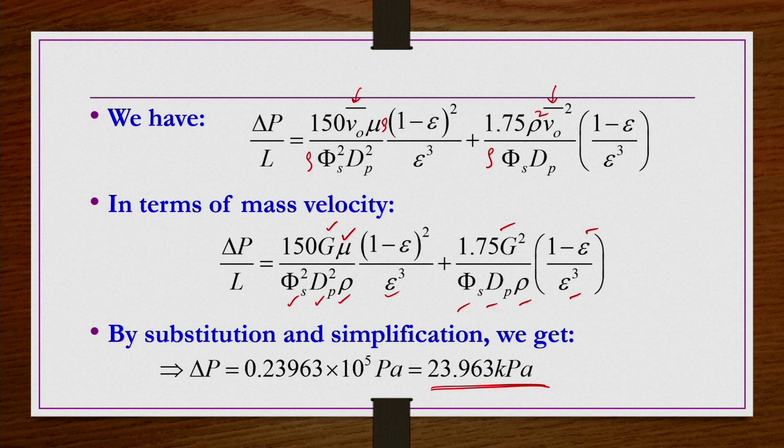Okay. So this is about the flow through packed beds, especially for Newtonian fluids flowing through packed beds made of different types of particles. We have seen how to develop the equations for small Reynolds number and large Reynolds number, and then combining them together we found the Ergun equation, which is valid for the entire range of Reynolds number.